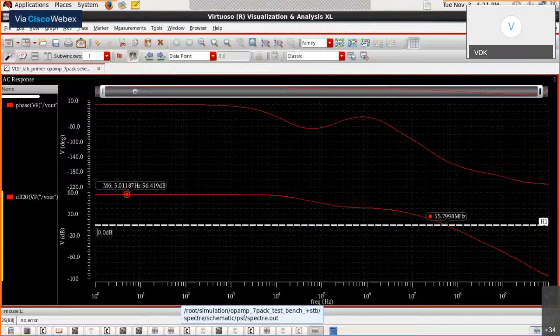And because our simulation results can differ from our hand calculation estimations by as much as almost 30+%. How good is the matching between these simulation results, maybe after post layout, and the actual devices? If we have done our iterations correctly and we have reasoned out what's happening, the match is very good. Anything within 10% is good.